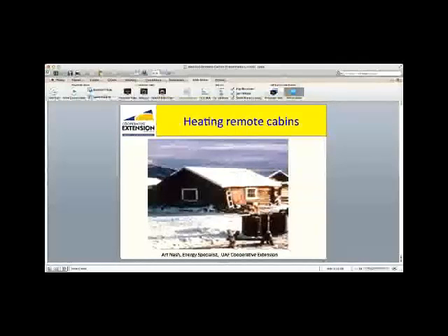People mentioned that they often saw shadows or ghosts every 16 inches, that they could predict where the next stud was going to be because it was just a dark line, the same thickness, 1.5 inch for a 2x4 or 2x6, every 16 inches. And that's because in that case, the studs are acting like a heat bridge to transfer heat from the inside of the house out to the cold on the other end.